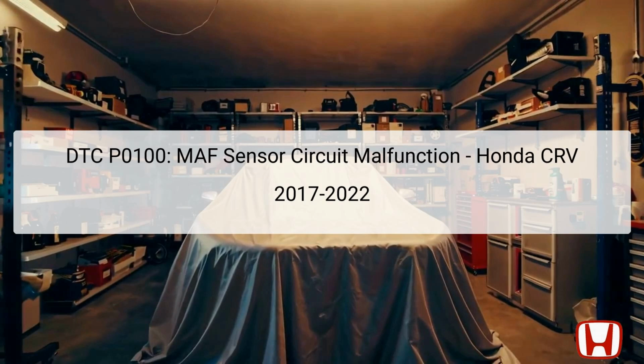This error code indicates that there is a malfunction within the sensor circuit, prompting the need for diagnostic inspection. The location of the MAF sensor is typically along the air intake pathway, either integral to the air filter housing or slightly downstream. When troubleshooting DTC P0100, it's essential to understand this background to ensure accurate diagnostics and repairs.